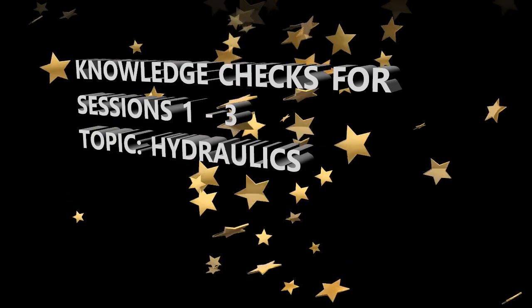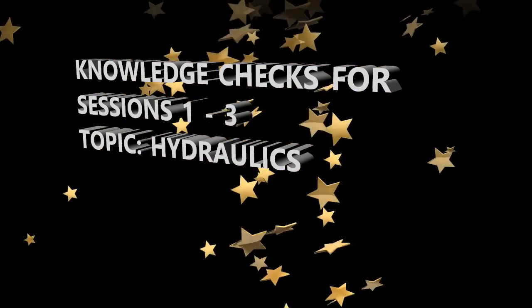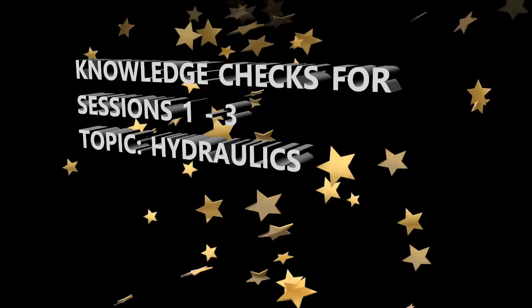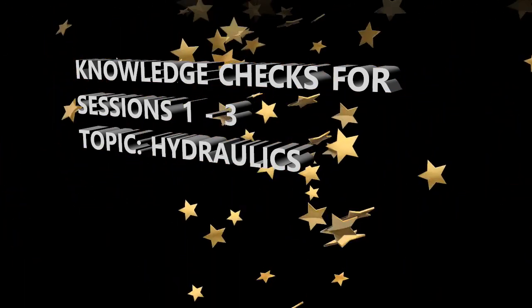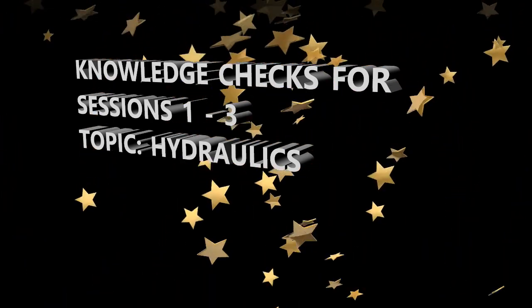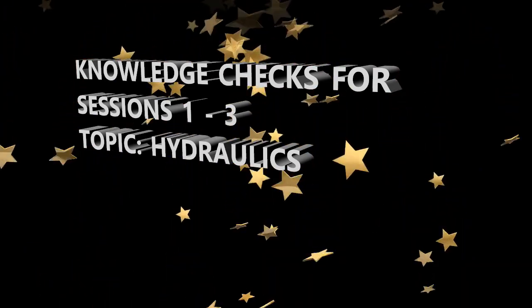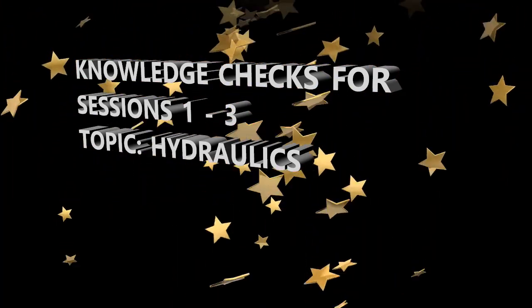Question number 21. From where does the PTU get its power? Okay, the yellow or the blue system? Okay, it's going to be yellow. Okay, and that's if something's wrong, we have some kind of problem with the green system.